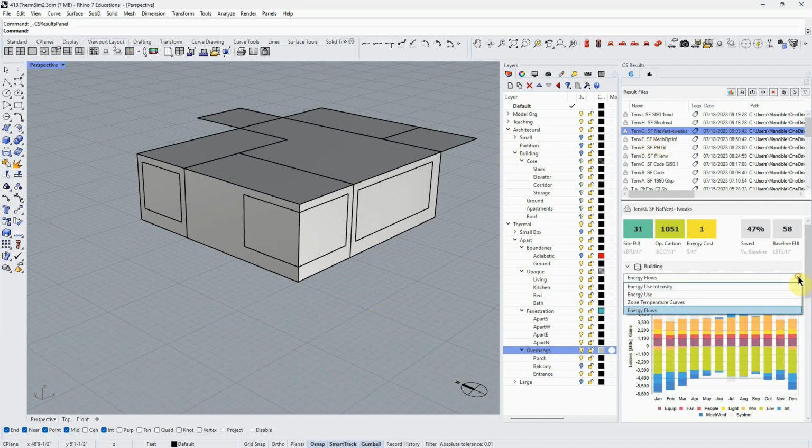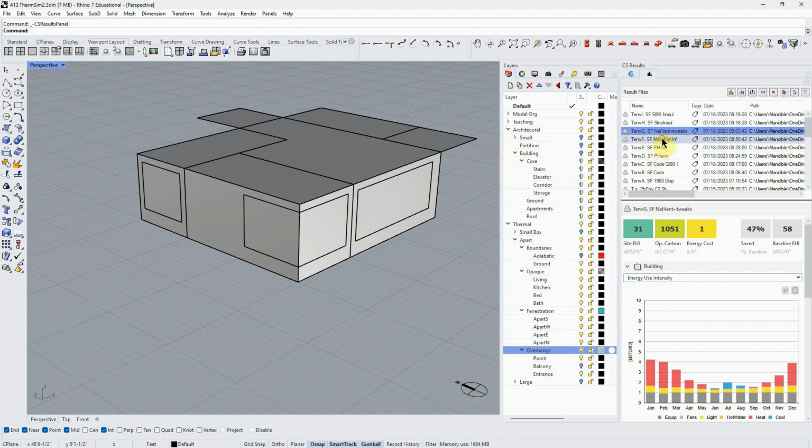And again, I'm going quickly here. Let's compare. Right here, yeah, we have a lot of cooling load. And so that's why I added the natural ventilation. I'll show you how to simulate natural ventilation. That is one of the main things adjusting that cooling load, because we're able to passively cool the space for different times of the year and not use power.